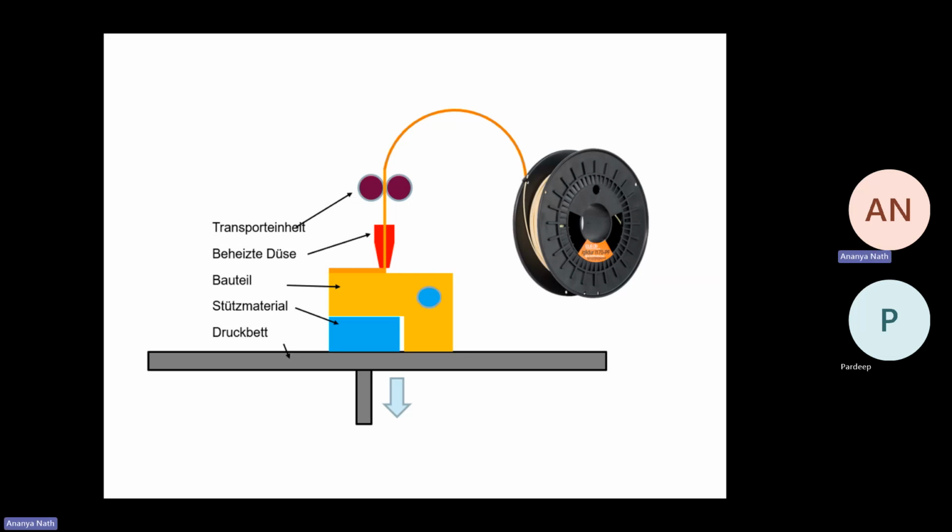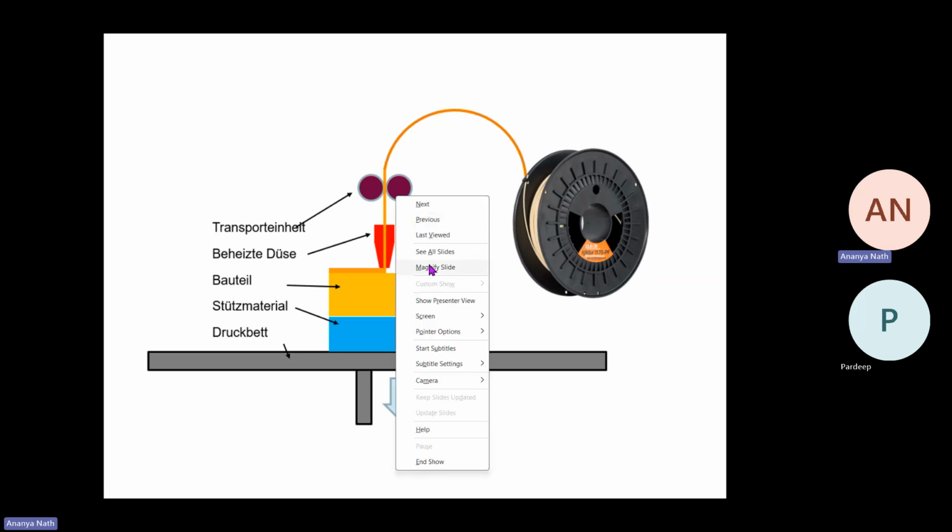If your CNC has only 3 degrees of freedom, like it can move in X, Y, and Z only, then you have to have support structures to provide mechanical support for the overhang features. But if your machine can move more than XYZ, like it can have a tilt axis, rotation axis, more than 3 degrees of freedom, then you can approach support free printing, where if your part needs the support structure,